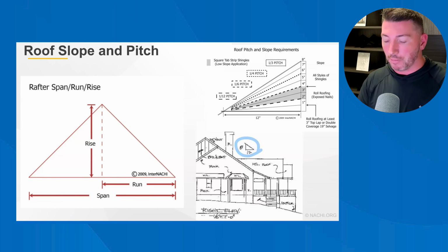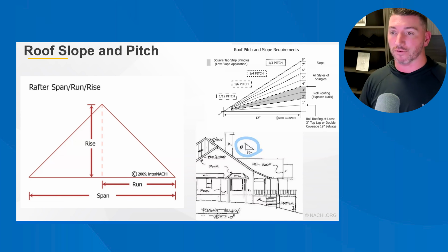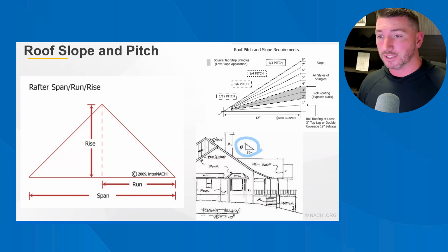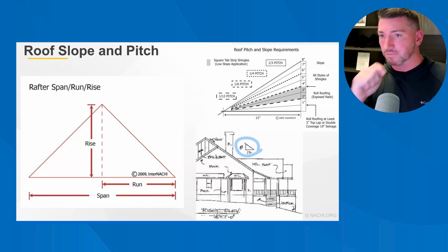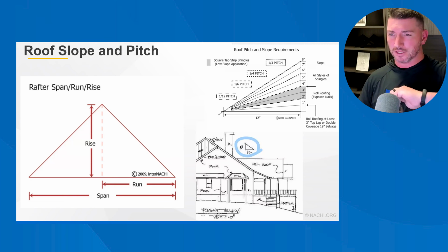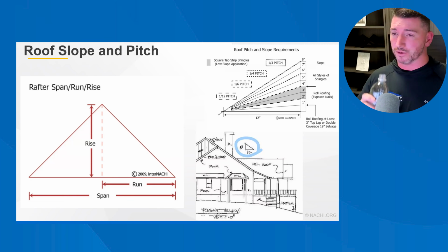There are a couple of categories of roof coverings or roofs in general. A low slope roof, or a flat roof, depending on who you're talking to, is 0 to 2. Then 2 to 4 is a funny area in the code where you can use shingles if you want to, but you're required to take other measures, like the minimum measure you would have to take to put shingles on anything from a 2/12 to 4/12. In some jurisdictions, it's 2.5/12 to 4/12, not including 2 as something you can shingle.